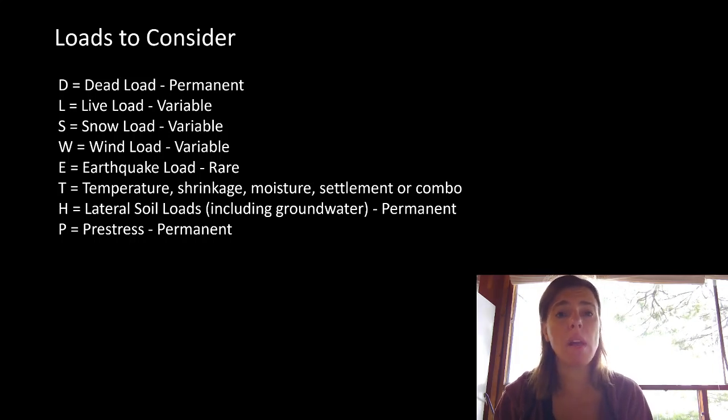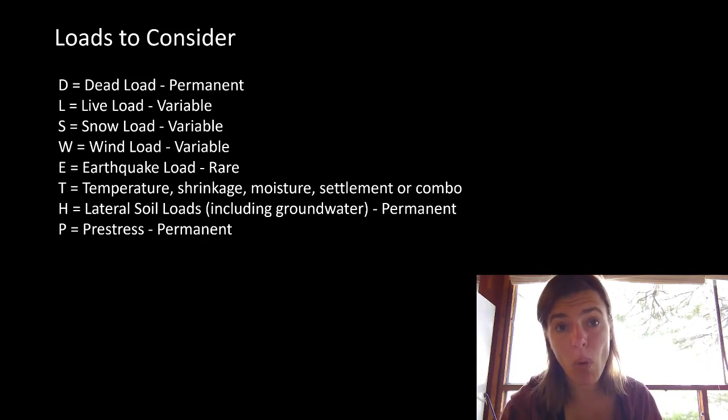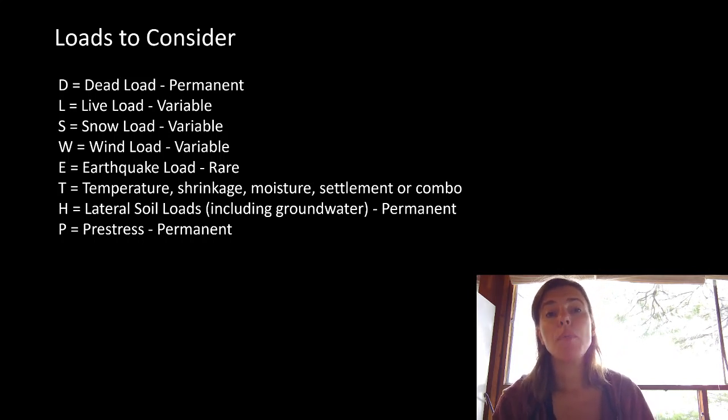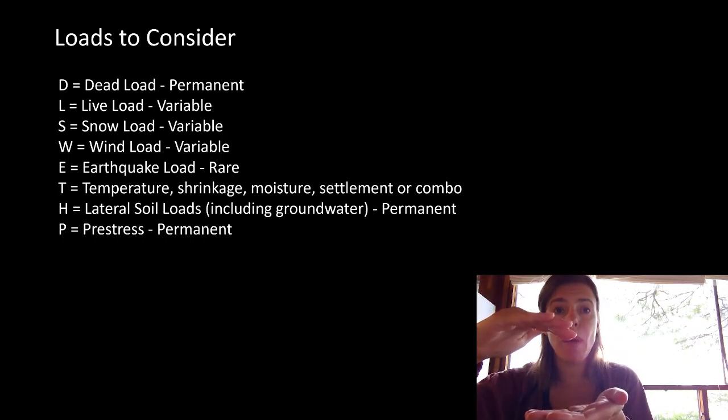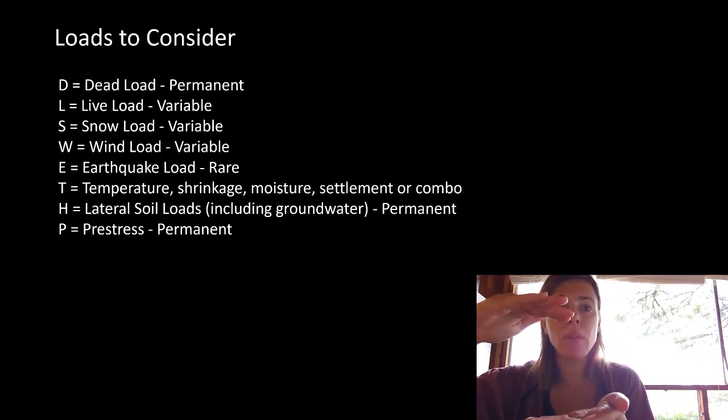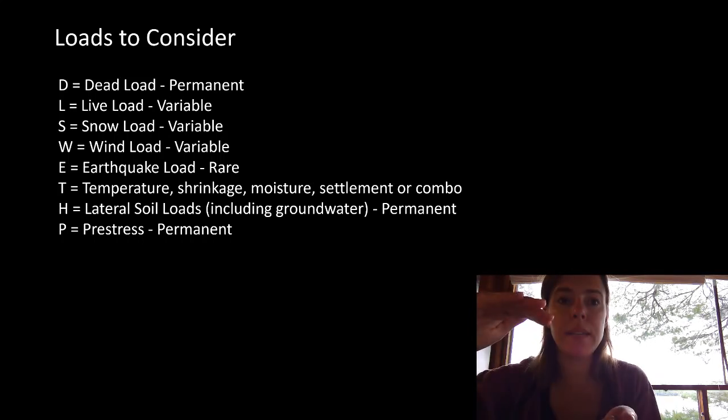And one thing that we didn't talk about at all in the core graduate course was pre-stress. And there are definitely some lectures where we're going to talk about pre-stress. That means before we've done anything, we ourselves apply a load into that system to help us remediate other things. You can imagine a column that somebody wanted to squash and we were worried about buckling, and they're going to push down with 1 kilonewton, but we know steel does a really good job in tension.